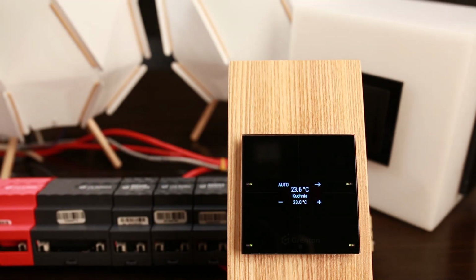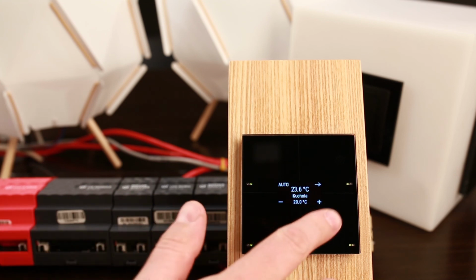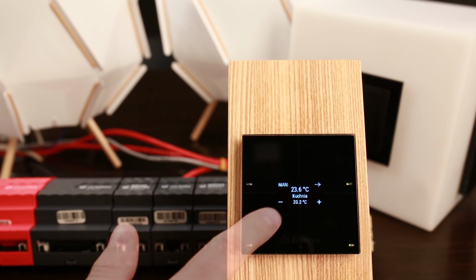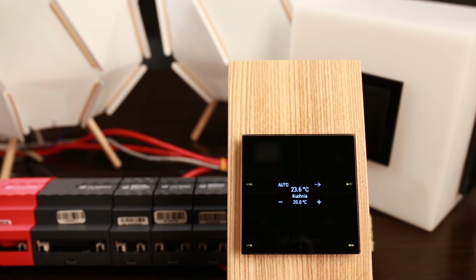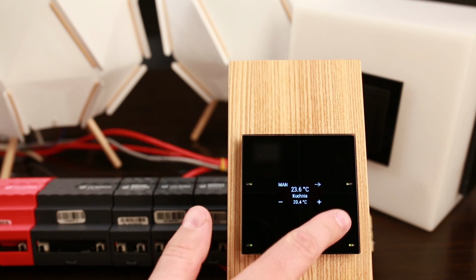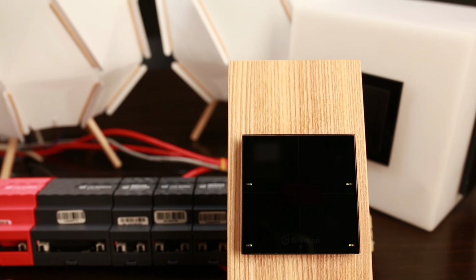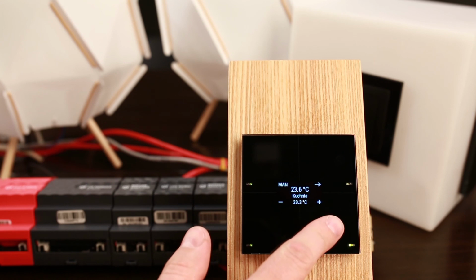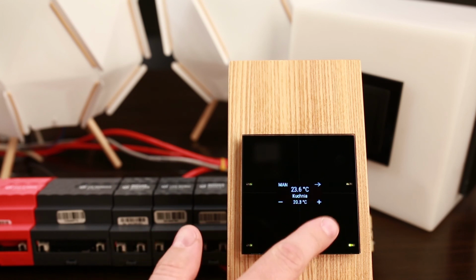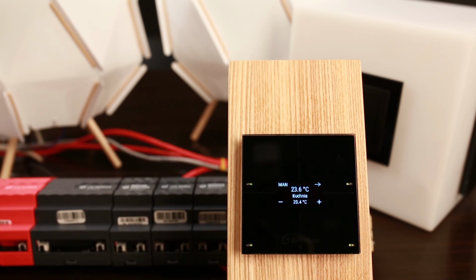The condition is off. If I hold this button for a longer time, it changes into auto, but if I change the temperature plus minus, it goes into manual mode. But with the button, I can change it to auto again. Auto means that the thermostat is in a schedule mode, i.e. the temperature it will seek will be in accordance with the schedule we set. Manual mode means that it will go to the temperature that you set with the buttons and will keep it permanently.